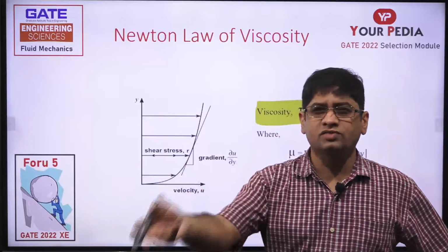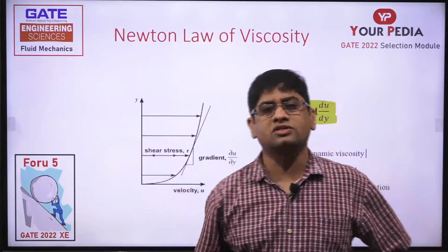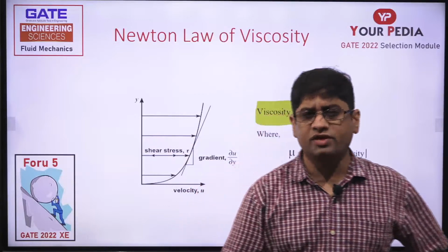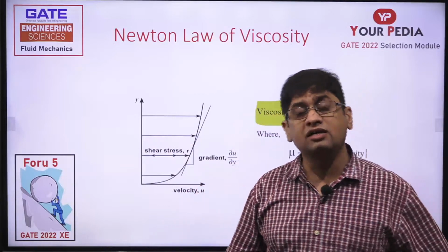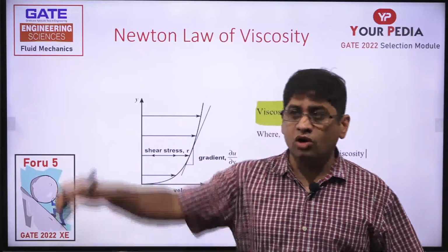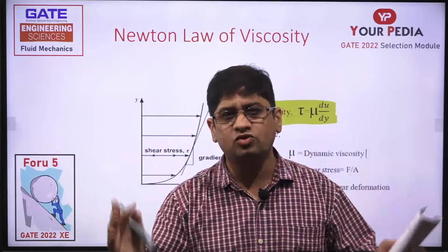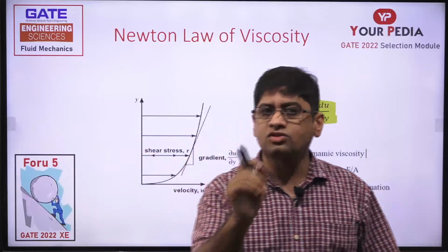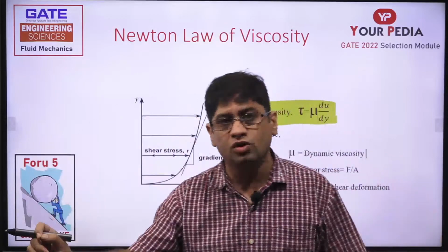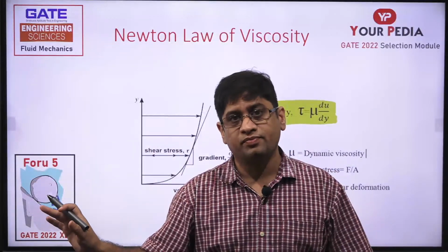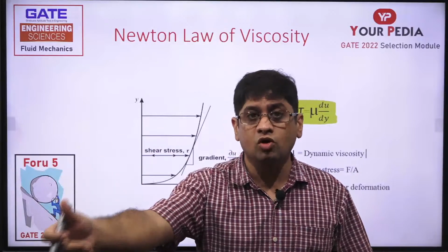Drag force on solids is actually friction. If somebody asks you what is fluid friction, the answer is: viscosity is the fluid friction. Why does it exist? It is because of intermolecular attraction. When the molecules have cohesive nature, intermolecular attraction, which eventually is viscosity, that viscosity leads to friction in the fluid. So friction in solid and friction in fluid are different concepts. Friction in fluid is because of intermolecular attraction.